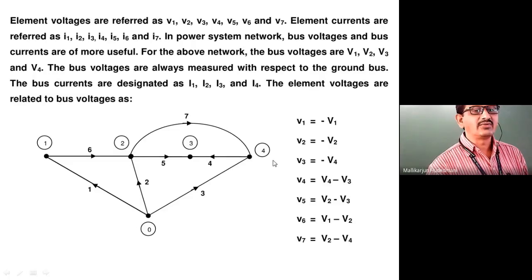And what is V4? V4 equal to 0 minus this. Or you can come by the other way. Then V5. V5 is the potential. Where is the 5? Element number 5 here. Difference between V2 and V3. Like in nodal analysis, what we refer. Any voltage between two nodes, if you find that, is the branch voltage, the differential potential, nothing but the voltage of that branch. This was seen by matrix A's approach.